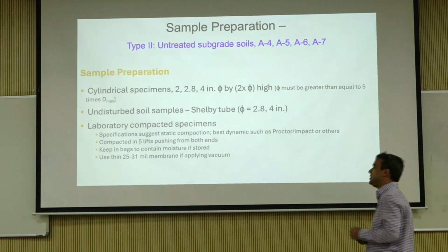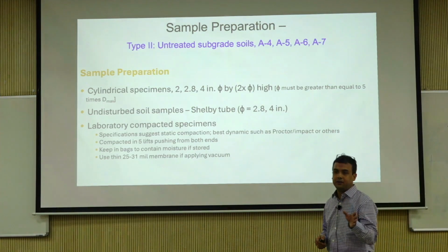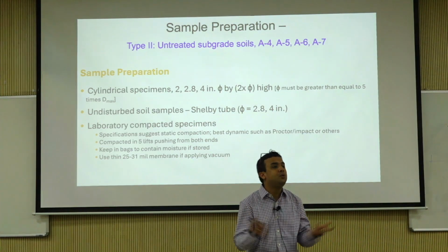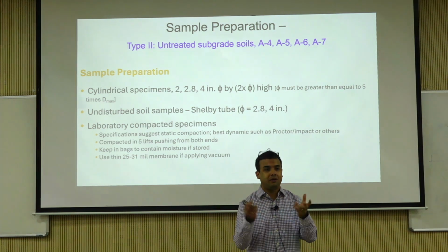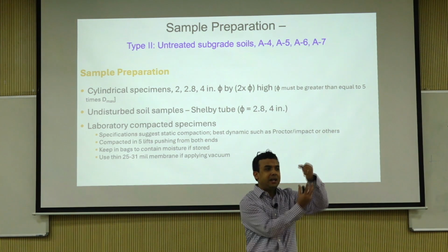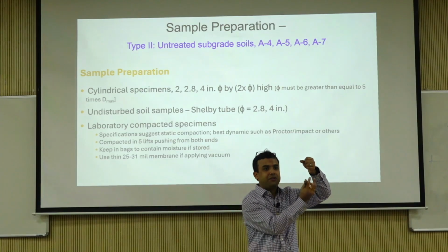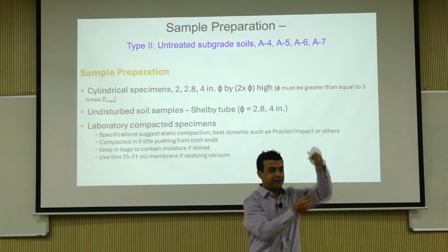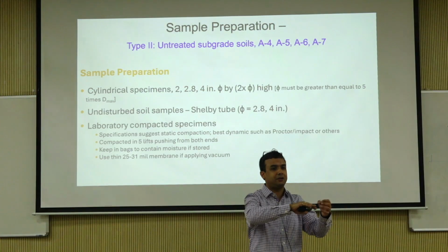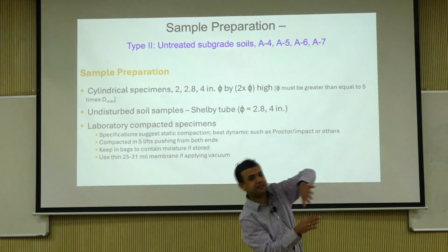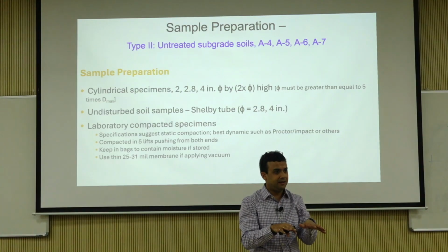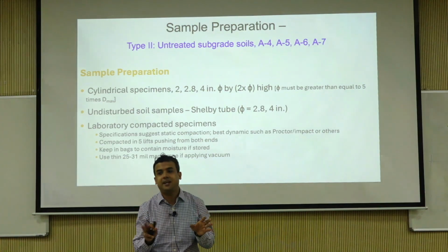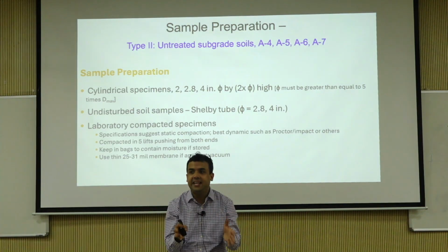Your achieved density is never going to be exactly the same as your standard and modified compaction and stuff. And there is a big difference also, folks. How do you do a Proctor test or standard compactive effort? You have a little hammer, right? What's the footprint of the hammer? It's only part of the mold, right? And then you drop it here, and if it is open graded or something, it bulges here. You drop it here, it bulges here. You try to play with it, right? So the Proctor test is not very representative usually of an aggregate specimen.